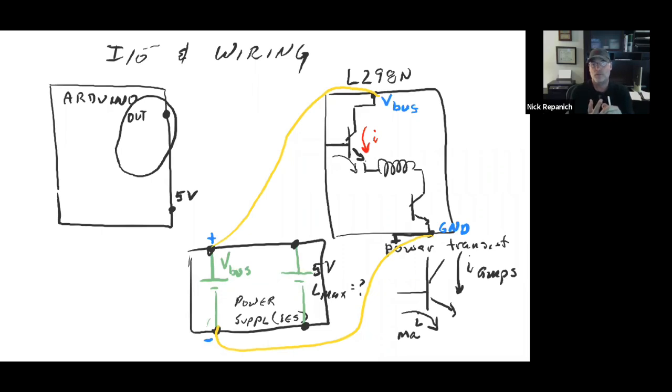A pump, an electric pump, like a well pump for instance, has an AC motor on it: inductive load, inrush current. The kind of circuit that we just drew here: inductive load, inrush current. This power supply needs to be a different kind than the 5-volt wall wart. If you wanted to run this off 12 volts and you found a little 12-volt switching supply designed for resistive loads, it would absolutely not work to drive that inductive load very well. I mean, it'd probably just blow it up.